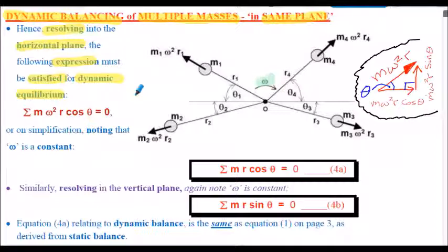This has m omega squared r cos theta, but it is a very similar format. So what we're doing here is resolving these forces into their x and y components, as shown on this diagram, a horizontal component and then a vertical component. Those are centrifugal forces, m omega squared r, and we're resolving into horizontal and vertical components as shown in the little sketch.